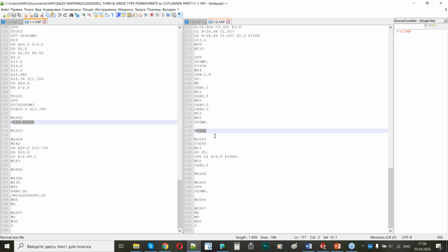After this command, the back spindle starts rotating at the same speed as the main spindle, and then I call my back spindle. This is the special code offset on the CNC to position the back spindle, because as you can see, it positions according to the part coordinate system, not machine coordinates. So it's a safety position, the clamping position, calculated from the machine setup. Then I will have the cutoff process with the Z synchronization special commands for this machine.